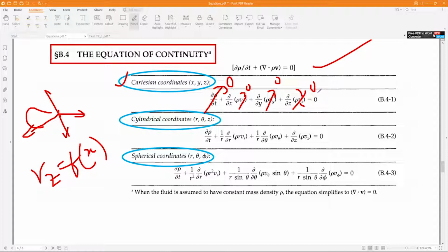So from the continuity equation, we did not get any equation, because the flow is incompressible. Sometimes in cylindrical coordinates you might get some relation, but generally you will not get one for incompressible flow. So this whole term is 0.